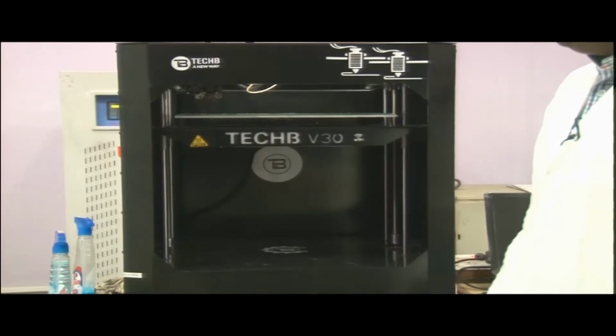Now this PLA thermoplastic is also more pleasant on the nose, as the sugar-based material smells slightly sweet when heated, as opposed to the harsh materials associated with ABS. When we heat ABS, the smell is quite annoying. In PLA, this is not the case. So this means that printing these parts is more friendly for the operator. PLA also seems like a better overall choice because it features a far lower melting point. The melting point of PLA is quite a bit lower than ABS.